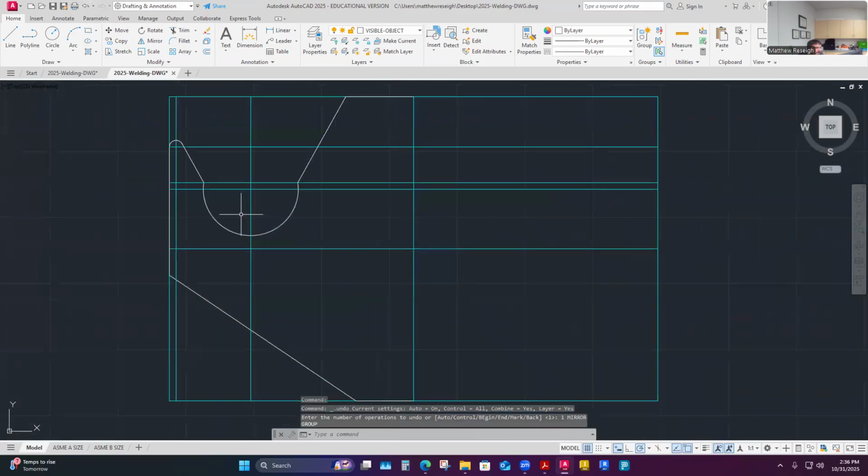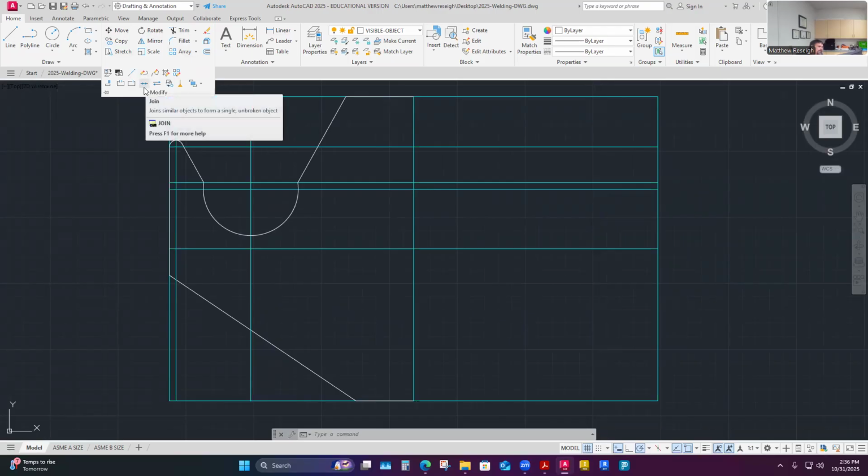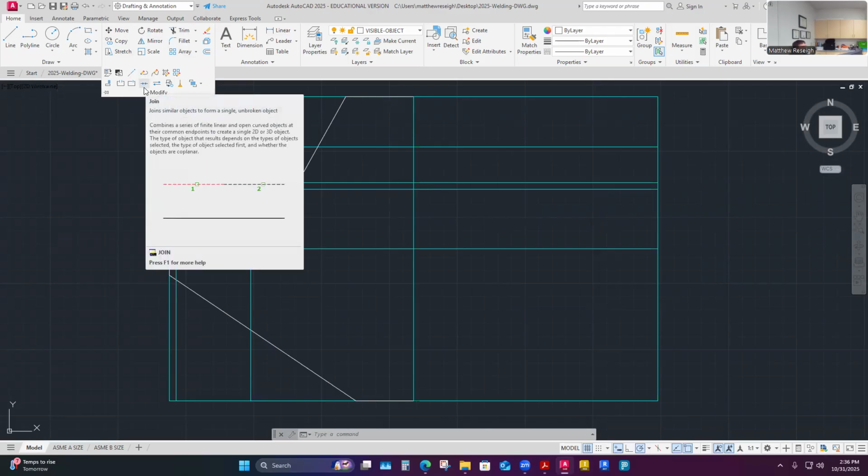What I do is I spend the time to join stuff into kind of a uniform shape. And so it's a buried command, but I wish it was more on top here, especially when you're building parts for machine cut. In this modify tab in the sub tab here, so this is a little deeper knowledge. Right here, this little arrows coming together is what we say join. It's just a command I use to join those so that eventually when I show you how this works, it'll only take me one click to select all that geometry that's going to be mirrored.